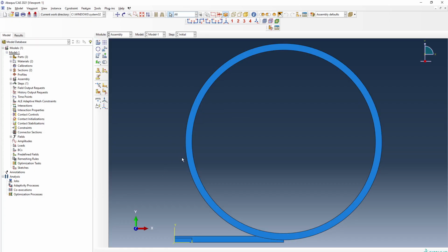Okay. So first I'm going to move the stock 500 mm to the back. Instead of 13750, I'm only choosing 500 mm of movement. This is to speed things up initially, and if everything is working fine, we can always redo the simulation for more travel of the stock before it comes to the rolling stage. So the starting point is 0, 0, and then I'm moving it back by 500 mm.